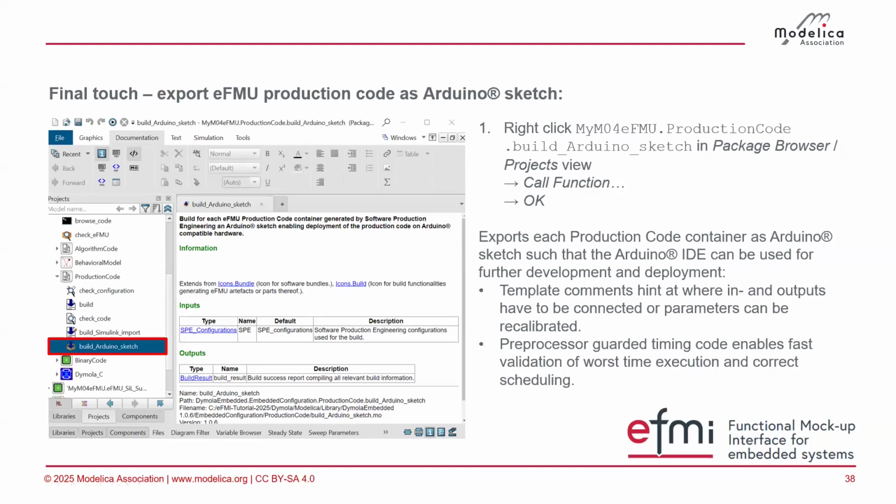And of course, the other thing you want to test is, does my code actually compute fast enough? Not the other way around. For example, I have a sampling period of 2 milliseconds, but the step takes 10 milliseconds. For that, we generate code so you can easily test this by sending out how long it really took to do a step. Then you activate it once and check: is my Arduino powerful enough? Does it execute my code fast enough? Okay, then you deactivate it again, the preprocessor, and from there on you're settled.